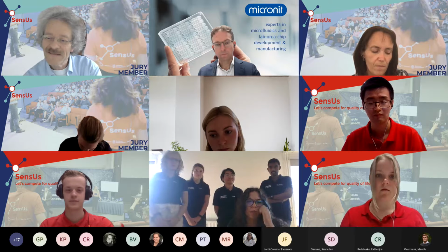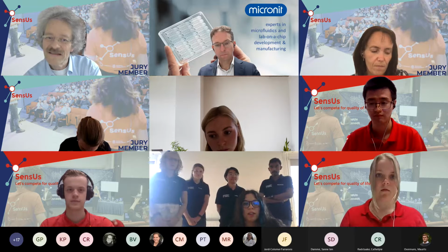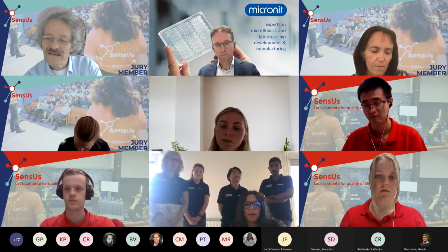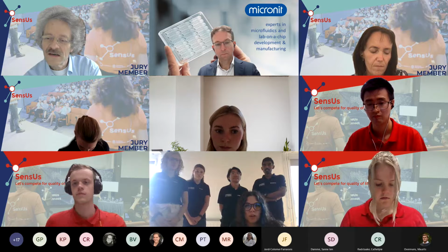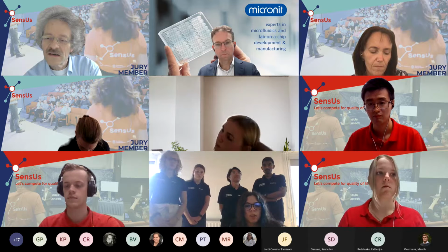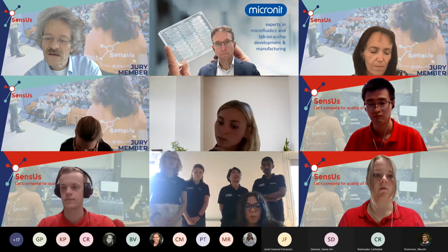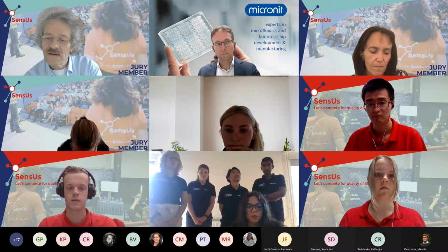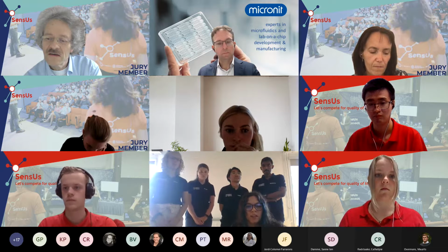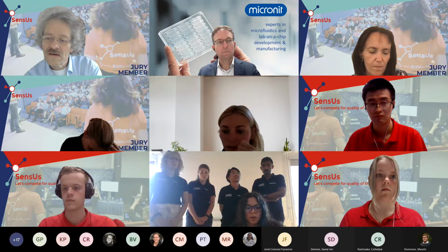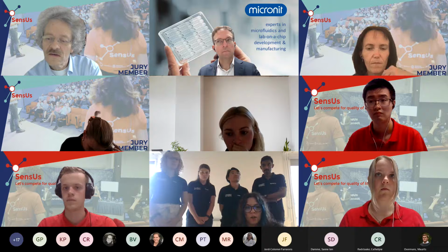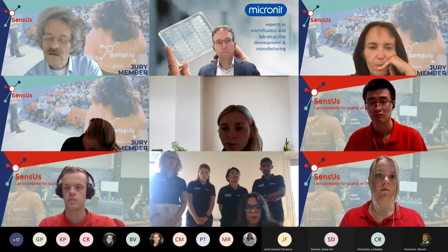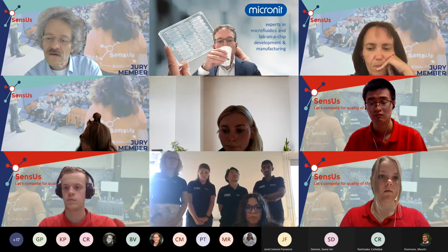Yeah, so one of the good things of the chip we're using is that we have multiple rings in each channel, so that allows for referencing. So this chip self-references. In one of the rings, there's no binding, so with this we can subtract a baseline. We can eliminate all the background noise due to temperature or any other noise, and just have the pure signal from the binding.